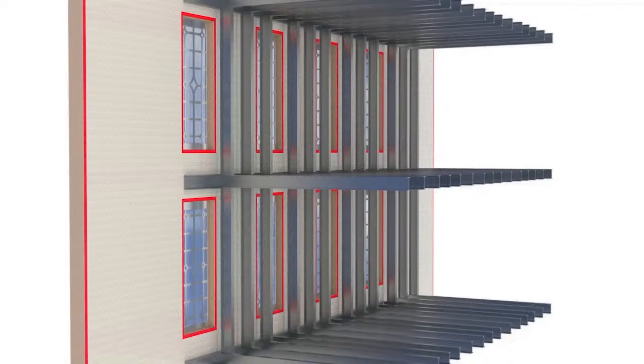Raptherm is installed on the reverse of the retained facade stonework in a similar way to many self-adhering damp-proofing membranes. However, as Raptherm is vapour-permeable, it does not adversely affect the movement of moisture through the facade stonework. This helps limit damage that can occur when moisture flow through older stonework is altered by upgrade works.